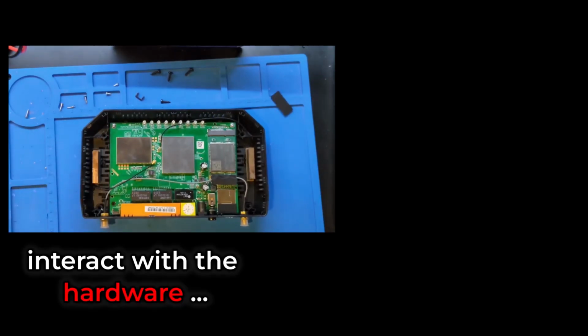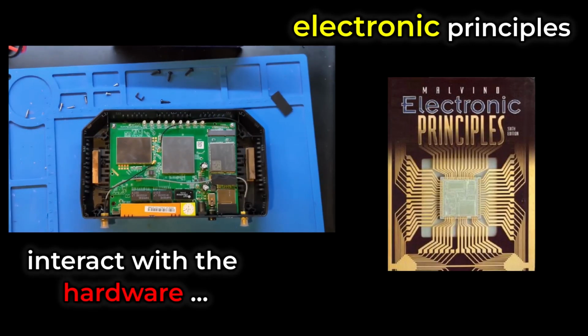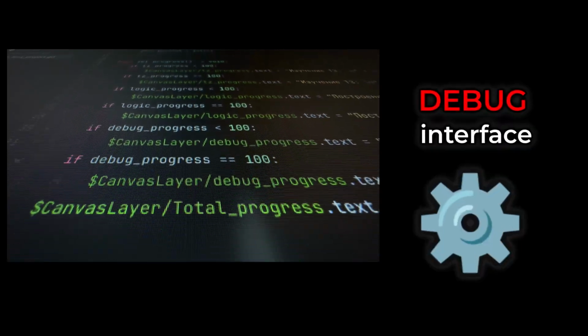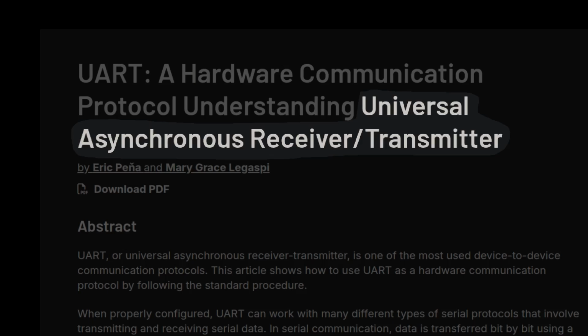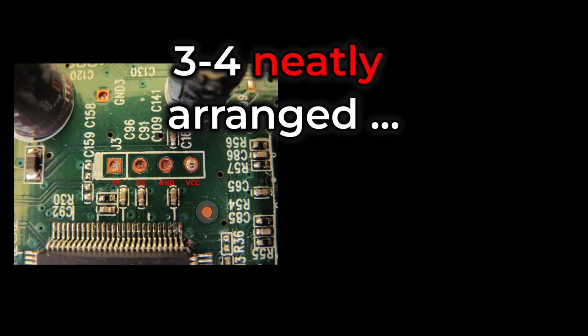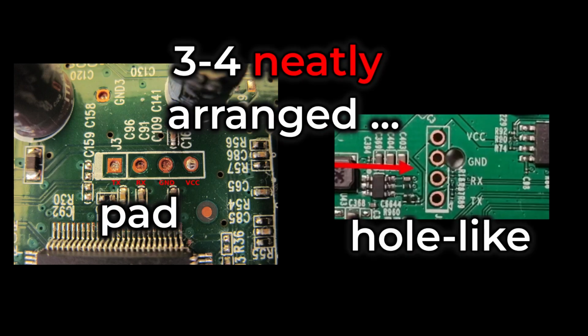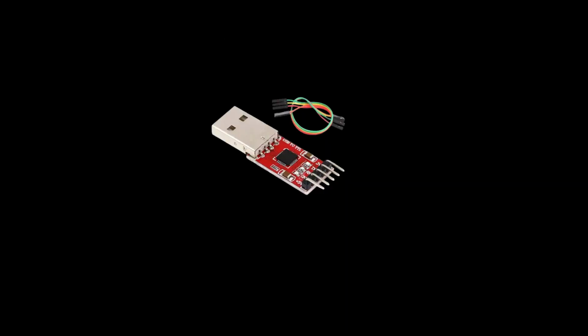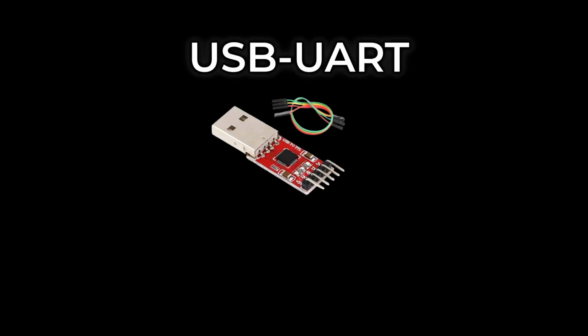interact with the hardware, which requires knowledge of electronic principles. A basic method to access the underlying software is through a debug interface, such as the Universal Asynchronous Receiver Transmitter, or more commonly known as UART. It will appear as 3 to 4 neatly arranged pad or hole-like interfaces. It will require a digital multimeter to probe the interfaces to map out exactly how we can connect to each pin. A special type of adapter, such as the USB to UART adapter, will be used.